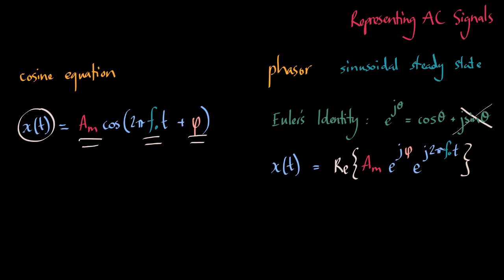As you can see, we've taken the exact same three parameters of amplitude, phase, and frequency and reformed them into a different equation, of which we only take the real part. The complex coefficient there at the start is the phasor, and it neatly contains the peak amplitude and phase angle disconnected from the time-varying part. A phasor defines the time-invariant information of the time-varying sinusoids. This makes sense because we've removed reference to the time.